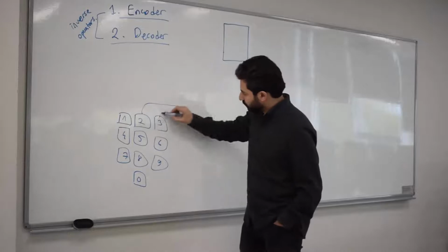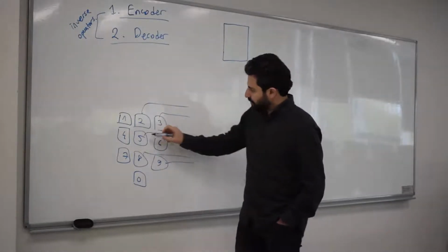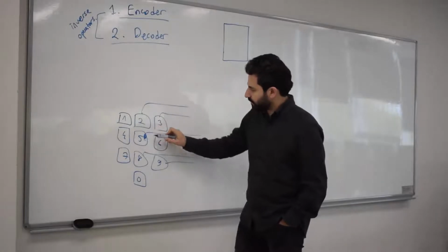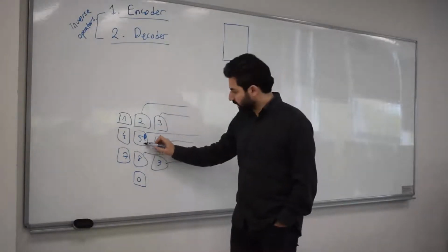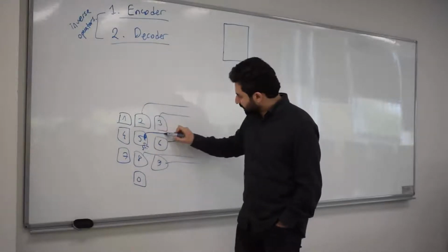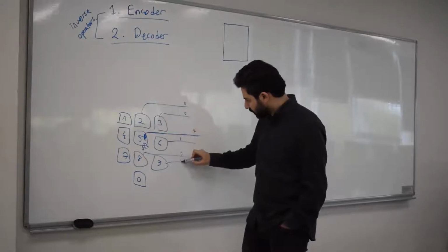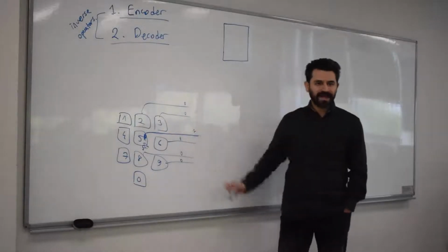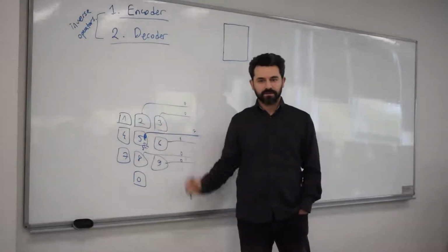These are all connected to wires, right? When you push, for example, 5, this closes the circuit that is connected to 5 volts, usually, and creates a digital 1, and the rest of them are all zeros. That's exactly what happens when you push a button on your phone keypad.